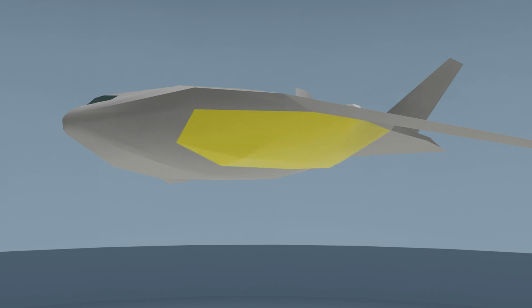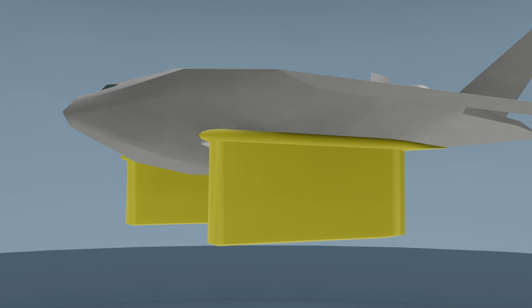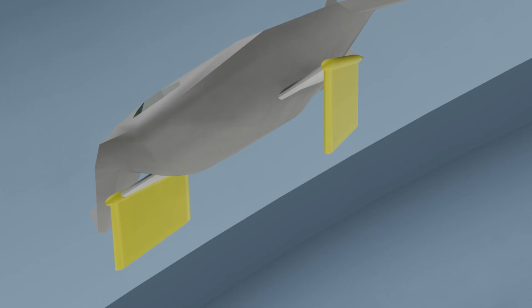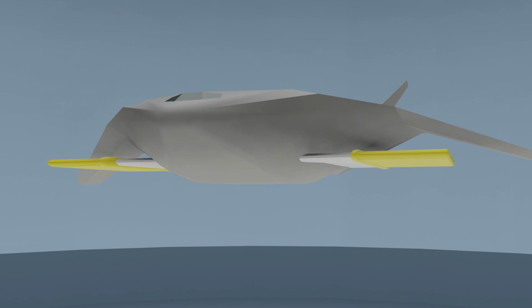For radar, AWACS aircraft, the antennas would have to be stored horizontally for takeoffs and landings, and then rotated 90 degrees downwards for operations. The antennas could be rotated more than 90 degrees if the airplane is going to be in a constant circling turn. But the two antennas have twice as much aerodynamic drag, twice as much weight, and produce twice as much aerodynamic forces on the airframe. Additionally, if the antennas can't be transferred to the horizontal position, the aircraft can't land. So the antennas would have to be jettisoned. And if you couldn't jettison the antenna, then the plane crew would have to put on parachutes, bail out of the airplane, and let the airplane crash.